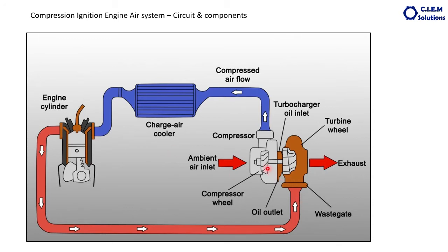Before the entry into the turbocharger, a very important component is the air filter, which is not shown here. I am going to talk about all these important parts: the air filter, the turbocharger, and then the aftercooler. There will also be an air filter restriction indicator, and some sensors, atmospheric sensors, boost pressure sensors, all these things. Let us move through the components one by one in detail.